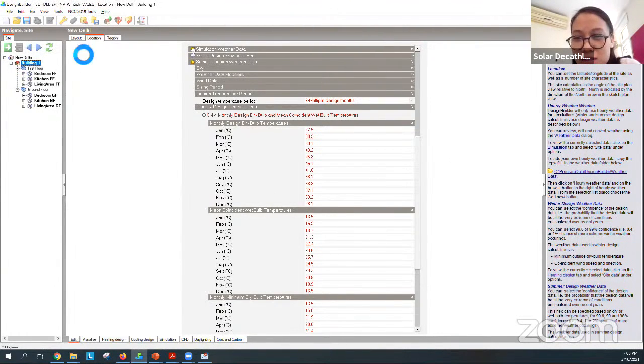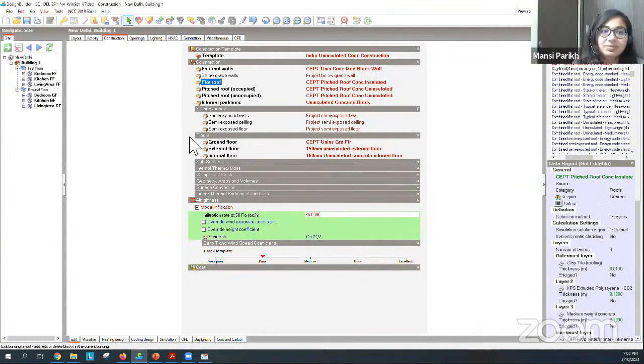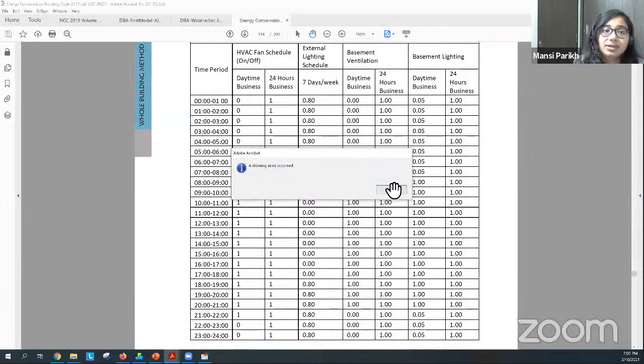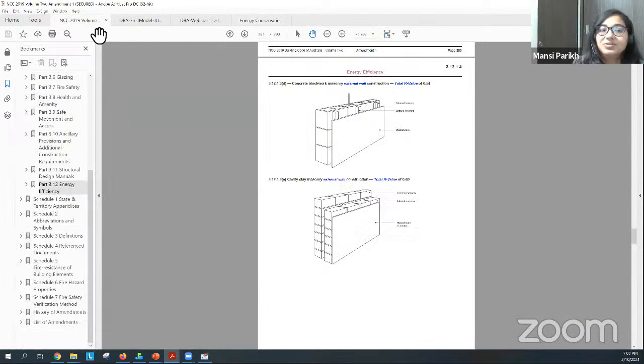Maybe he's talking about what the thermal performance results would be like. Then probably we'll have to simulate. There are two kinds of cavity walls: one is aerated and one is closed. When you are calculating the U value, you can account for that open or closed cavity. Based on that, I think you can simulate in Design Builder and check how well it is performing as compared to the insulation.